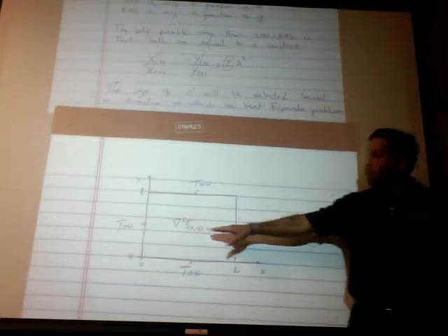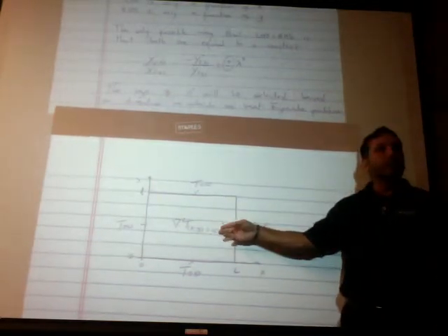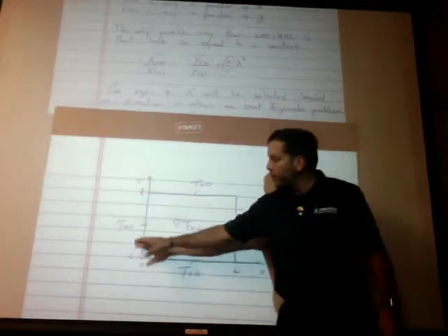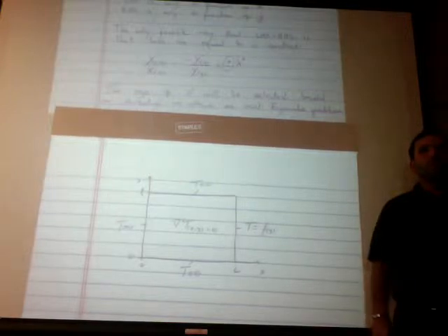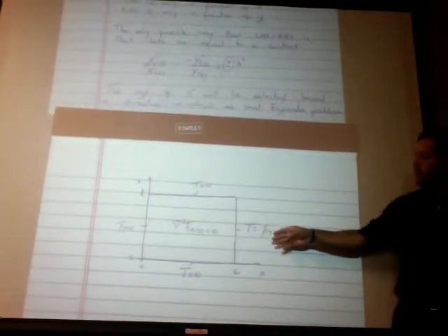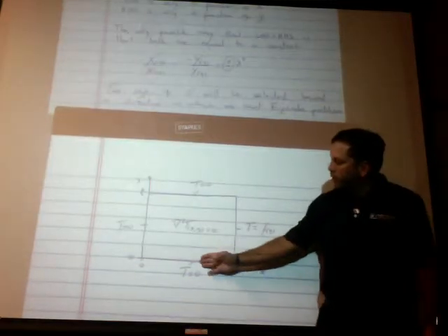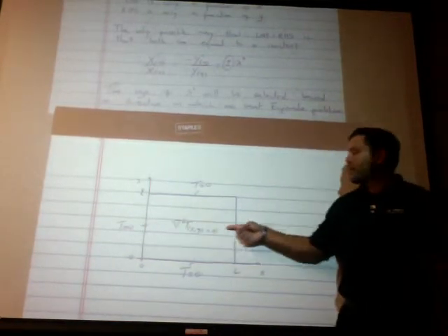If that condition on the right-hand side were also 0, there is no possible way for the solution to be non-trivial. Okay? If this was a 0, nothing is driving this problem. The solution is 0, period. So the only thing driving this problem, the governing equation is homogeneous. There is no energy generation internally. All these equations, all these conditions are 0. The only way of taking this out of equilibrium is the right-hand side non-homogeneous condition. And I'm just generalizing it as f of y. It can be a constant, it can be whatever number. So now we have one homogeneous direction, that's the y direction, and one non-homogeneous direction, that's the x direction.